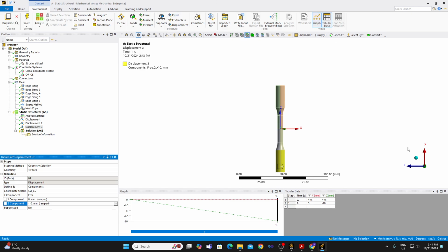Now if you look at it, at the top surface there is a constraint about the z-axis, which means this specimen cannot move along the z-axis. That is one constraint. But if you fix the entire top surface about the z-axis, it cannot also perform rotation about the x or the so-called y-axis. So that actually is 3 constraints in one go.